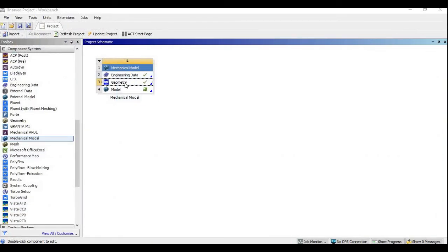Now it closes. Now if you see, what happens is, even though you made a step file, Ansys will only read the step file. It does not read the material properties. So that's the main problem. In Ansys, irrespective of what material you have assigned in Solidworks, when you convert it to a step file, it never reads it. Okay. So I hope that is clear. So you will have to insert the material separately in Ansys.